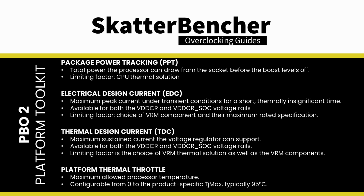Platform thermal throttle allows the user to decrease the maximum allowed processor temperature. The configurable values range from 0 to the product-specific TJ max, which typically is 95 degrees Celsius. Lowering the thermal throttling point is generally not recommended, as it will negatively impact your performance. However, it can be helpful if you want to run a temperature as low as possible.